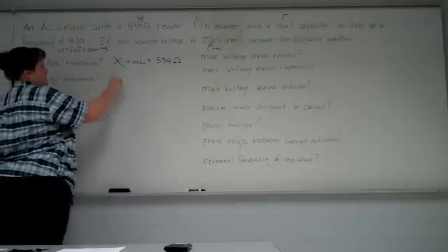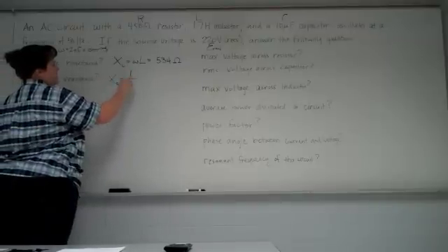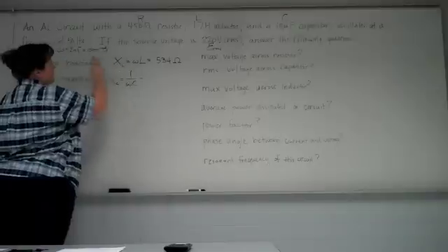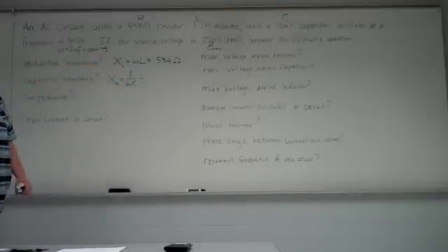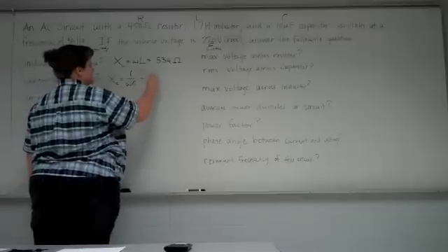Capacitive reactance. X sub C. 1 over omega C. So 1 over the 100 pi times 10 microfarads. That one ends up being 318 ohms.